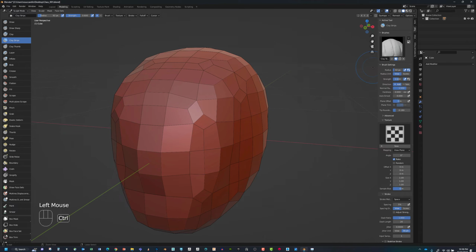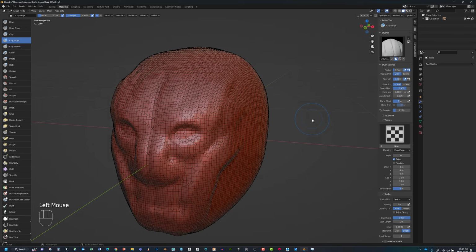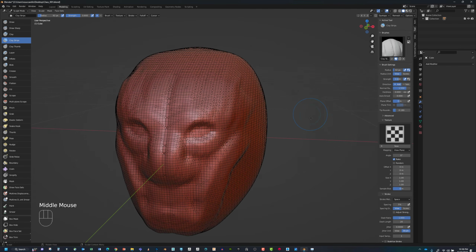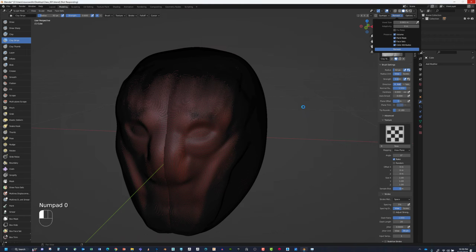So let's hit undo, and then we'll go back to remesh, and I'm going to make this a much smaller number. I'm going to go from 0.1 to 0.01, and then click remesh, check that out, see what the difference is here. So still not enough, so we need to drop down quite a bit more. So then I'm going to go to the next level. I'm going to go 0.001 and try that, and then click remesh and see where we're at with that.